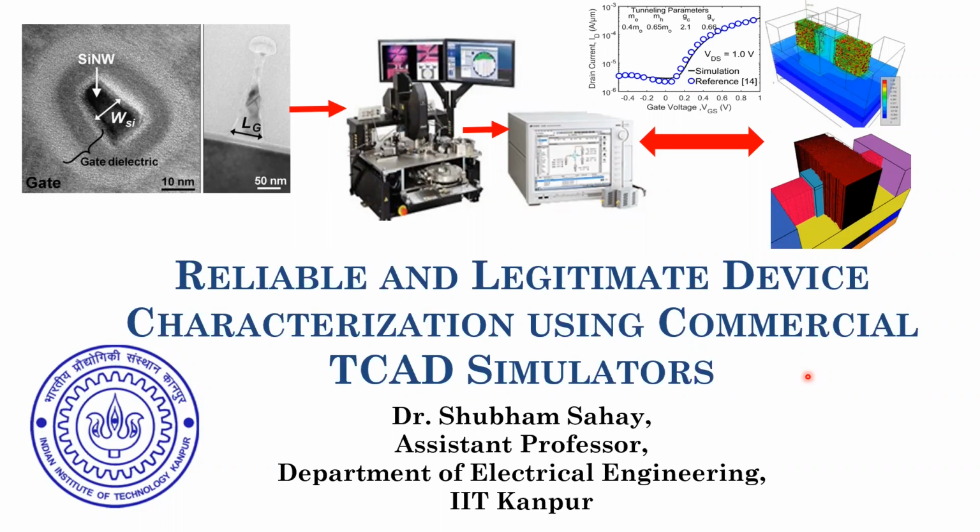TCAD is a numerical solver, a mathematical solver. You give it any input, it will definitely output something. So if you give it garbage input, or an input which is not at all relevant to your device, it will definitely give you some result, but that result itself would be garbage. It won't be legitimate. So in this talk, I will tell you the practices to make your TCAD simulations more reliable and legitimate, so that reviewers can believe them, and so that you can publish more papers or analyze more semiconductor devices.